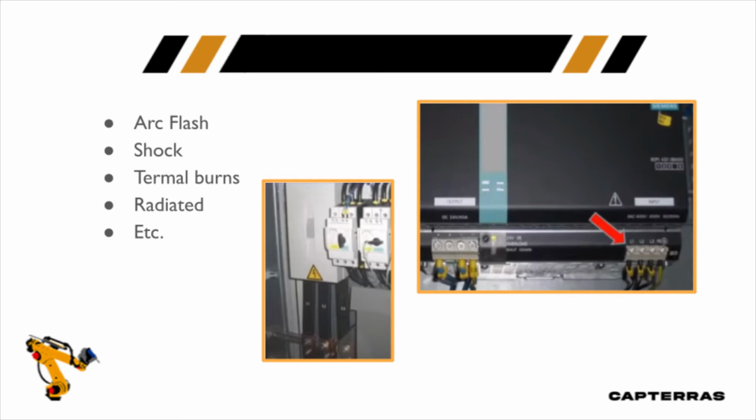But yet you get over to the production equipment, and here we have a technician, maybe that's only working on 24 volts in that cabinet. This on the right we can see here's from a power supply, and I've got a red arrow there. The technicians were only trained to work on 24 volts, and they weren't even aware there was 480 volts in the cabinet. Now, there should have been a sticker right on that cabinet indicating 480 volts, the source.